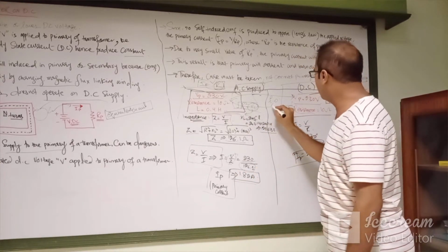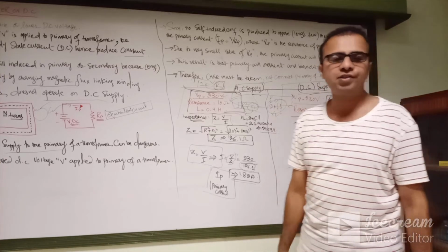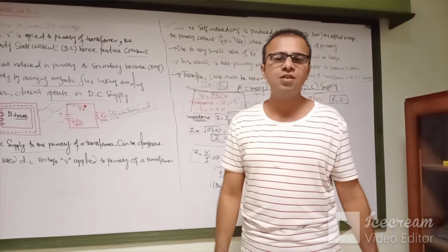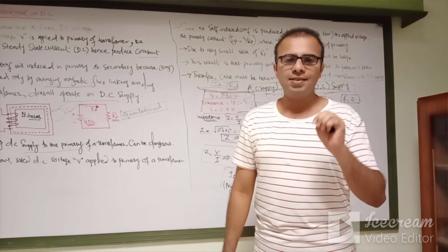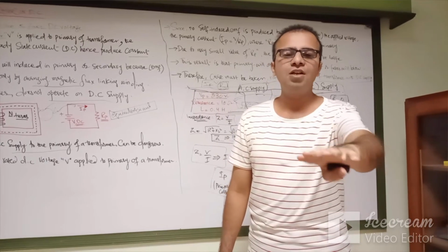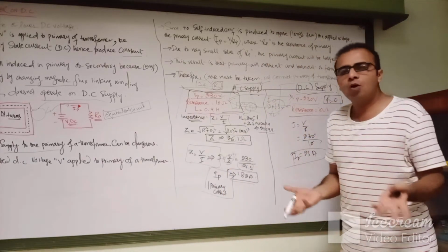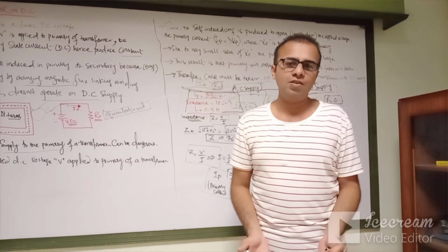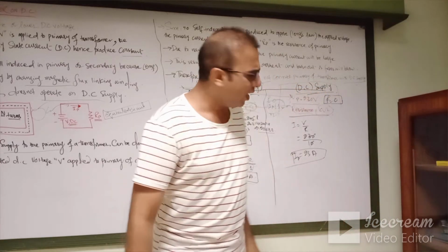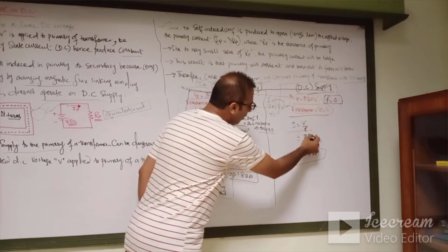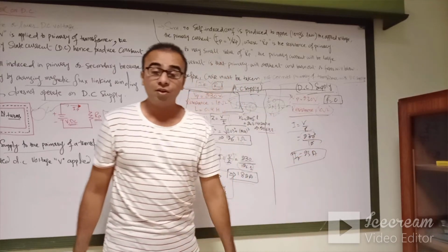If the frequency is 0, then what about the inductive reactance or the impedance factor? It is 0, because if the frequency is 0, there will be no change in the magnetic flux within the winding of the transformer, so no EMF will be induced in the windings. So we only take the resistance factor in the windings, which is 10. Now according to Ohm's law, I is equal to V over R. So we have V, 230, divided by just the resistance, 10, which gives 23 ampere.